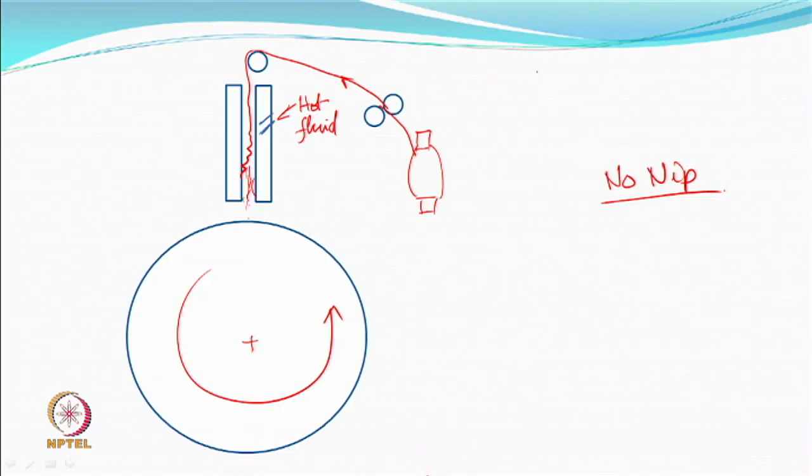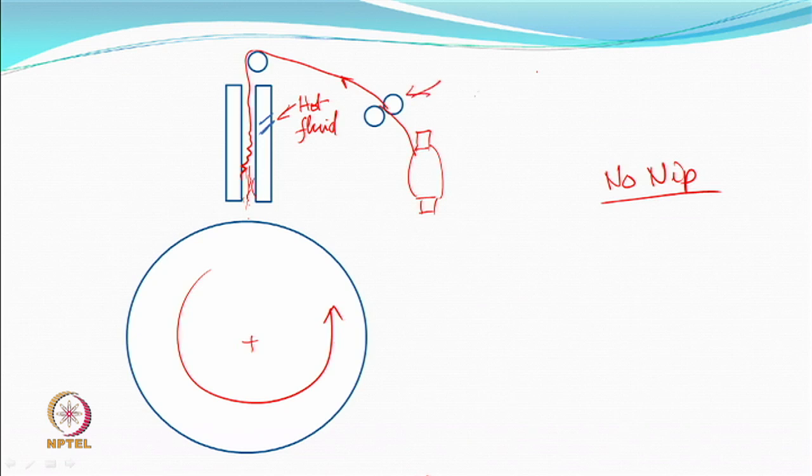So, the speed of this roll, this is a big roll, will be decided by how much overfeed you want to give, because whatever speed is there which is governed here, of course there will be guides and everything else, you just keep feeding, because this is sucking, it will pick up anything that you give, right. So, you give 20%, it will take 20%.